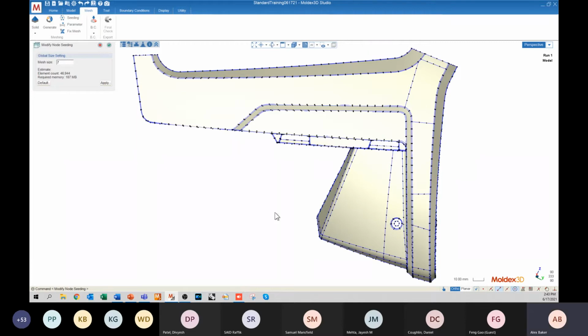All right, the reason we have such a specific rotation command set is because we want to normalize the size of the part geometry to our computer monitor. So this actually takes out the size of the part from the equation. This could be 2 millimeters long. It could be 2 meters long. I wouldn't know the difference because I've normalized the size of it to my computer monitor. This allows us to set the node size spacing consistently for every part geometry that we bring into Moldex3D.